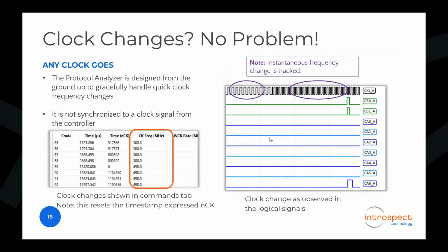And then I think the topic of clock change is something that we have discovered over the years. We started developing these solutions maybe 4 years ago, and as we started getting into the implementations, we realized, especially for LPDDR, more so than DDR, no real system will run at a constant frequency, right? So especially smartphones, you'll have frequency changes. As we are showing here, you'll have frequency stops as well that I'll get into in the next slide. And these are typically very difficult for test equipment to track, right?